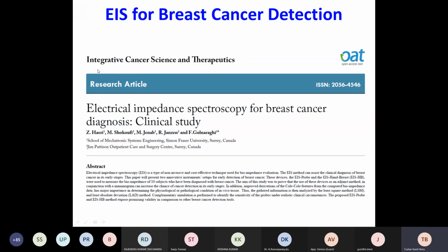or breast cancer. Whenever a biopsy is done, the breast cancer tissue or any cancerous tissue or tumor can be taken for laboratory examination, and with the help of microelectrodes, one small sample of the tissue is also used for detection of the impedance, and that impedance will be compared with the healthy tissue impedance, which will give us a clear difference between the cancerous tissue and the healthy tissue. So that is called impedance based biopsy. That work is going on, and it is under research also.